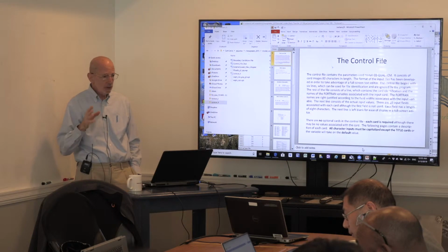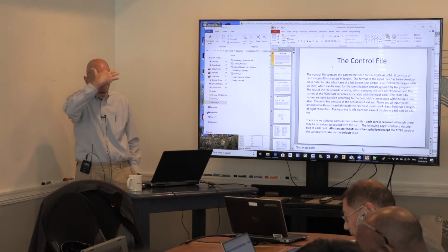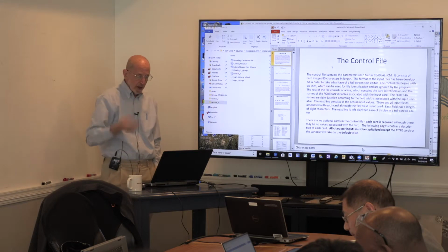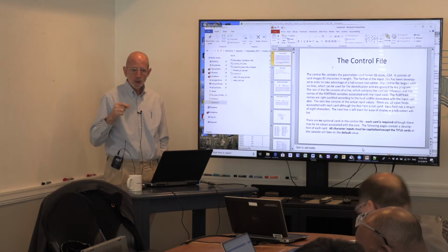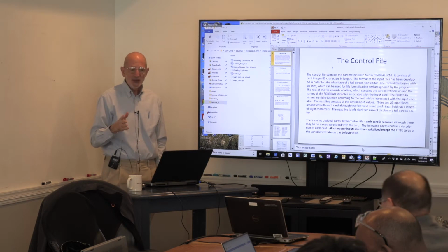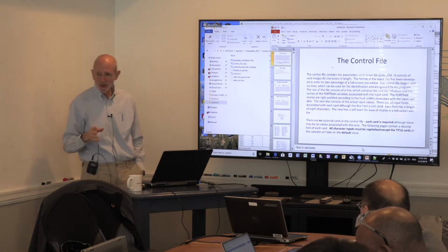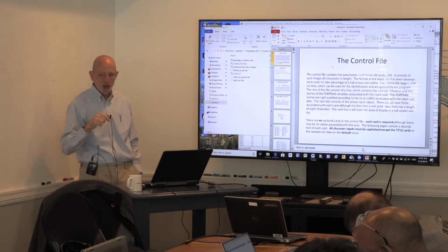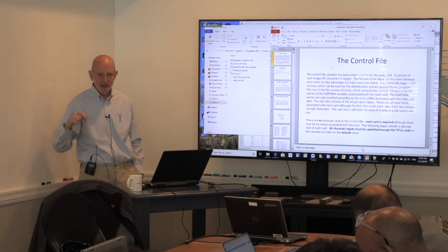So it's the master file. And it's hardwired. It's called wqm_con.npt input. Don't change the name. You can change it to anything you want, but the model isn't going to run because in the code it's hardwired to look for wqm_con.npt.